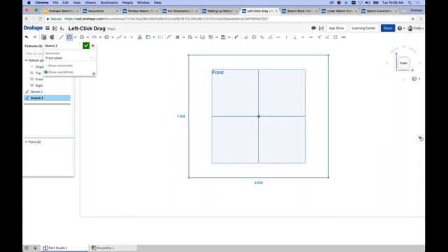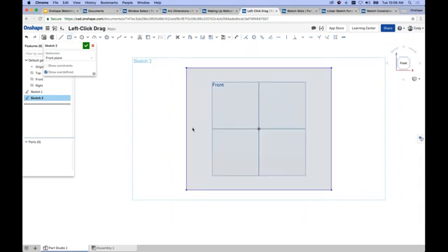So let's just sketch a center rectangle here. So here's a center point rectangle. And what I want to do is fillet the corners. I want to fillet them to roughly that size that I'm outlining there with my cursor. I don't know what that size is with respect to the rest of the sketch. And I can go to the sketch fillet command and just click the point, but it's going to default to a certain value, right? So if I left click this point, it's just going to default to some value, in this case, 0.25, right?